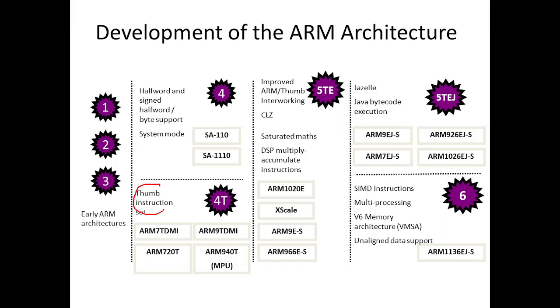This is thumb instruction support. What is thumb instruction support? Thumb instruction means there are different categories of instruction: 32 bit instruction, 16 bit instruction. In this type of instruction, we can use the half portion of an instruction, and when I require 16 bits, I can use that 16 bit for some type of instruction. That's why it gives flexibility, so it reduces the memory of the program. That's why these different types of thumb instruction are available, and they are supported by our architecture.